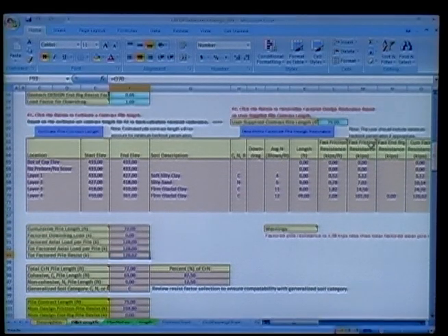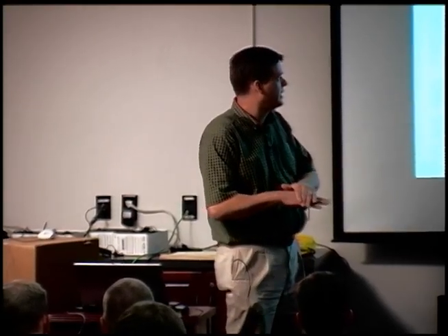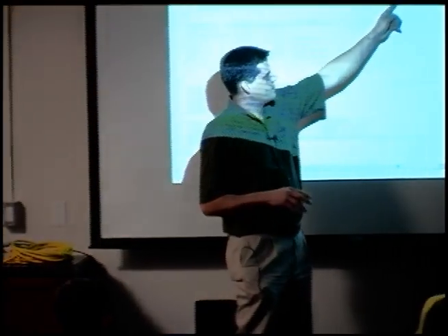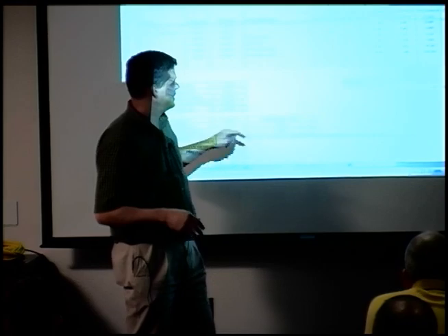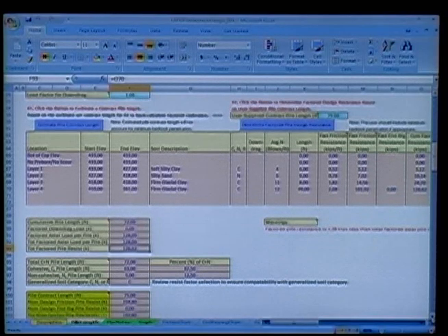Yes or no. One quick thing I want to mention up here, I better mention. I have a note somewhere. Okay, if you do an estimate pile contract length and you have rock, it's not going to add on that recommended extra 5 or 8 or 10 feet because it's going to hit that rock. It says, you got capacity, I'm done. That's partly why I put this in here, because if you hit the rock, you want to probably put that in as you move on down. So let's say you hit, I don't know, some good rock, and you want to add your 10 feet, so you put in 85 feet instead of what got figured over here, and that'll show up in your note. So there, I do note that here. You just got to be aware of it as you're using this.